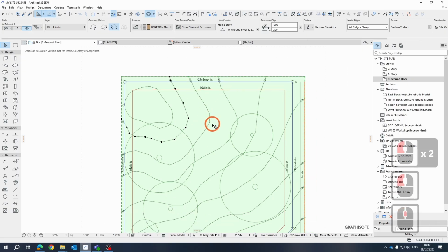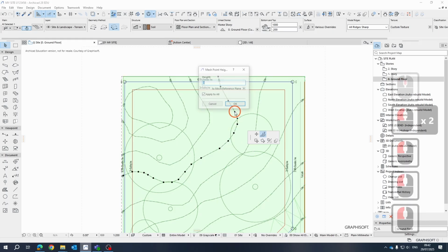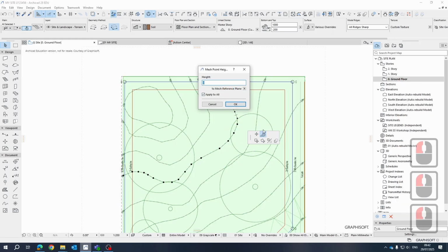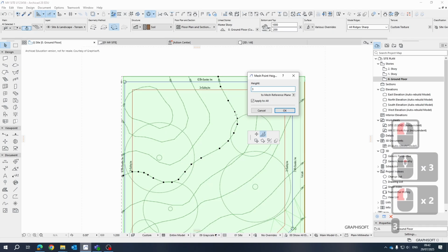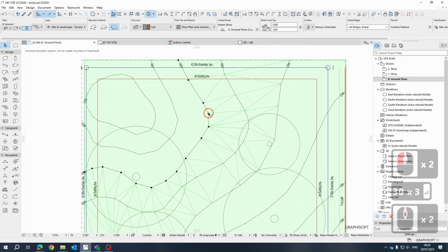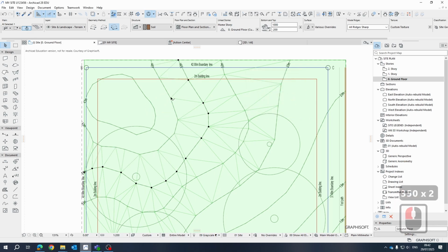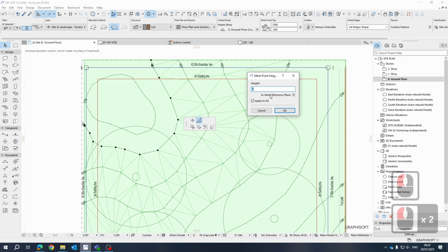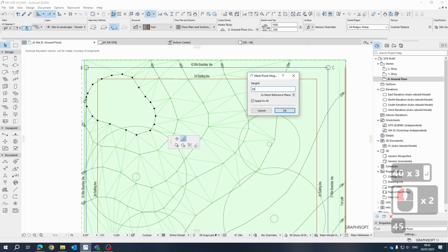So I'm just making sure that my ridges are 3,500. Okay, and you can see it's brought a lot of the information through from that file that we've had. So I'm just making sure that one's not incorrect, so those ridge heights must be 3,000. Okay, so let's change those ridge heights, those must be 3,500. Press OK. Okay, so now you can see I'm able to add these now. So it was just reading information from that file below, so just be careful.